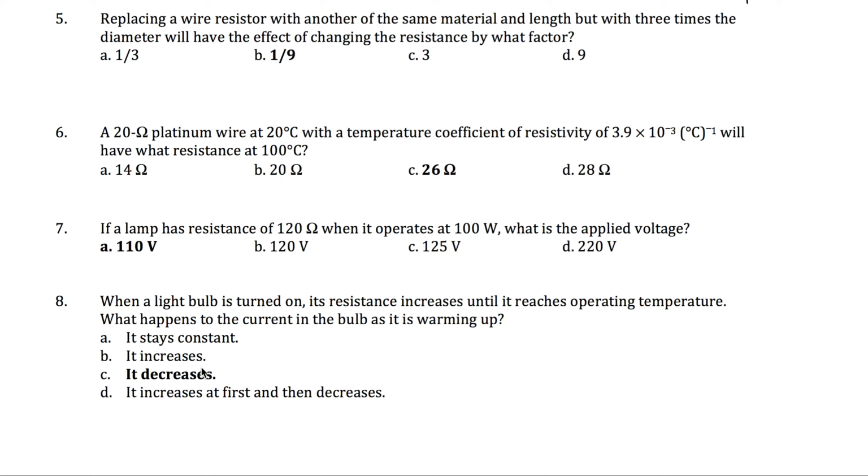So this is very similar to the your turn example that we did in class. So you're changing some of the variables. You want to find what's the relevant equation. The relevant equation is the resistance is the resistivity times the length over the area, because you're changing the characteristics of your resistor. So the thing is that this time it's telling us diameter. That's not one of the variables, but we know that the area is related to the diameter, because the diameter, I'll call D, is equal to 2 times the radius.